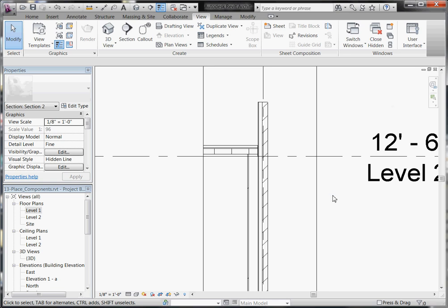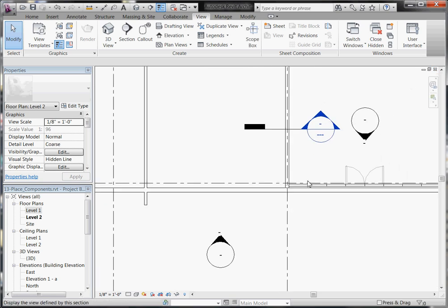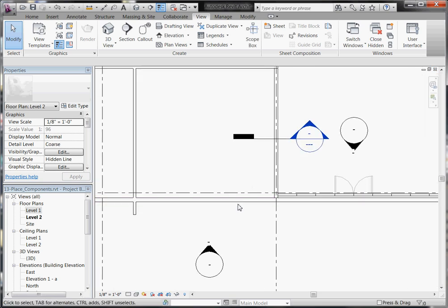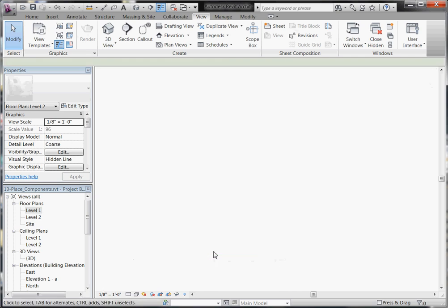Finally, the last method I know of is another modeling method. It's a way of changing the wall itself, and that is, I'll close out of this section here. This method is good for creating wall openings or the shape of the wall itself. So for example, if I want to create an entryway, an opening through this wall without having a door in it, then a good method to do that is to actually edit the wall's profile. So I'll go to an elevation view of this wall,